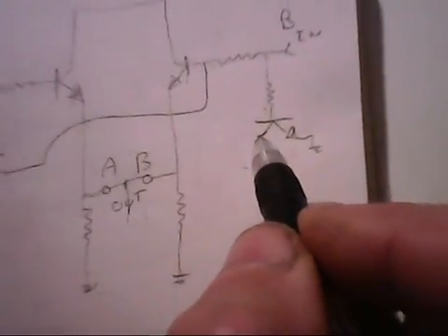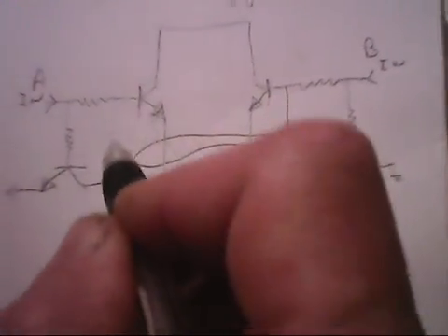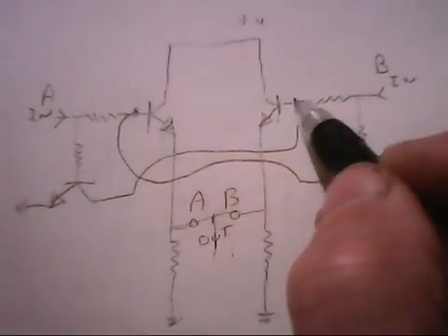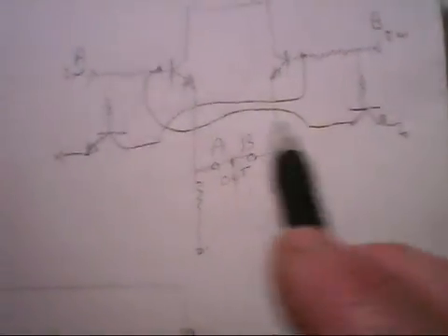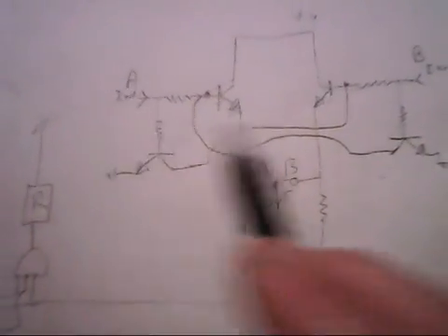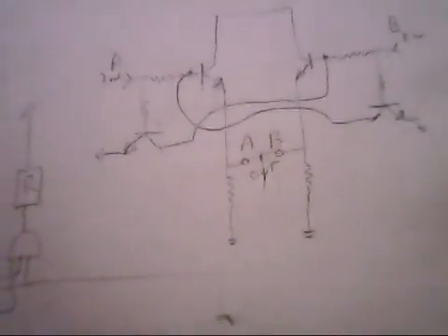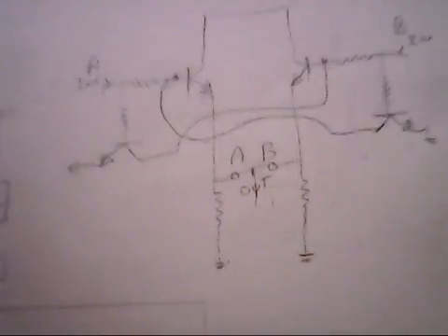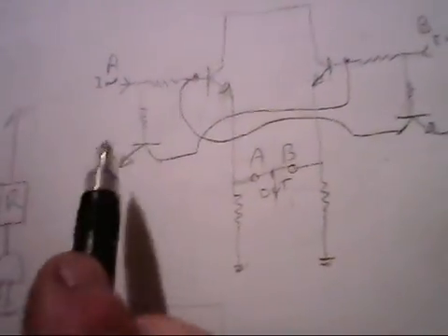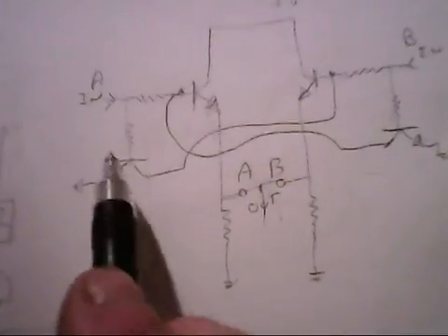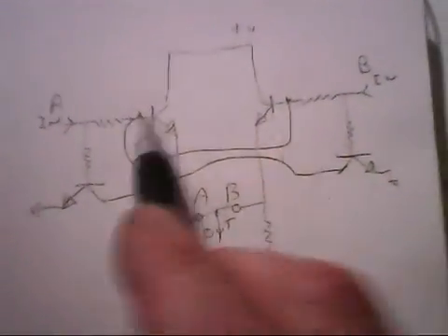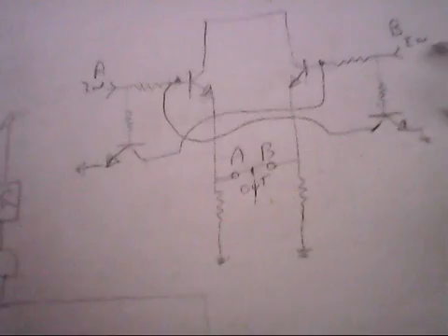When this transistor here is cross-coupled to the base of this transistor here, then what happens is this transistor turns the base of this off, and this transistor turns the base of this off. So if B goes high, this goes low because the collector goes low to there. So what we have here is cross-coupling. So here's what happens now. When they both go high, then both of these transistors come on, and when they come on, they turn off the output transistors. And that cross-coupling produces the exclusive part of the OR gate.